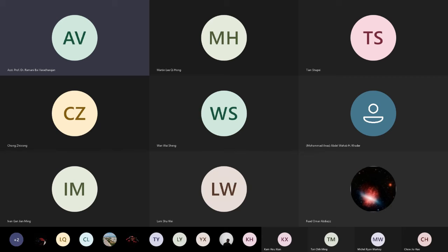No, there are two brackets. If the load is acting, it will be shared by two brackets. That's why we have to divide. Same as the one we did in pins. Pins also we divided the load.